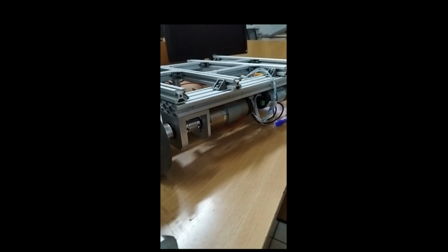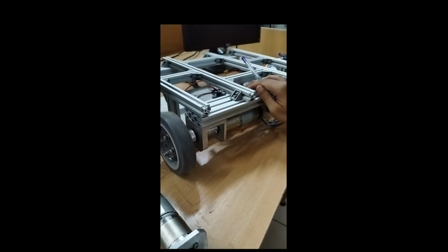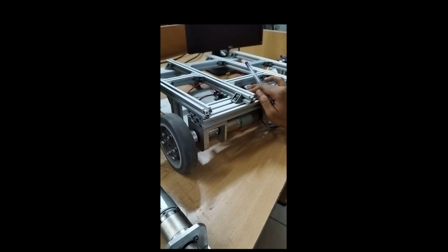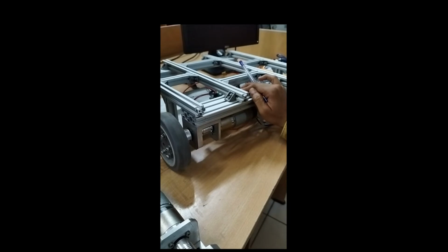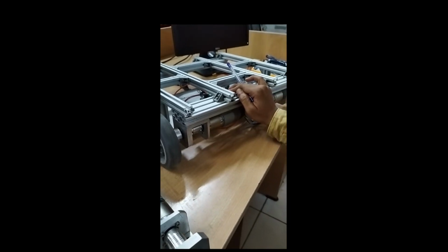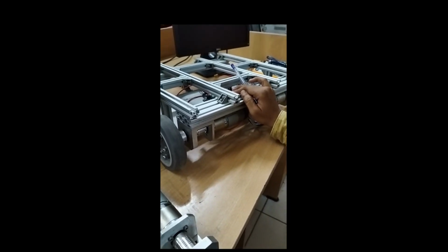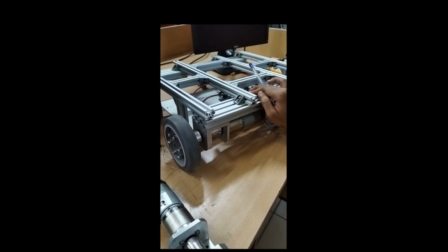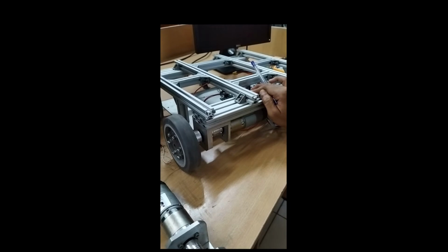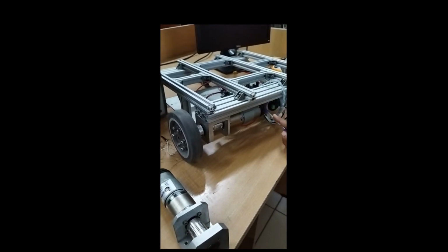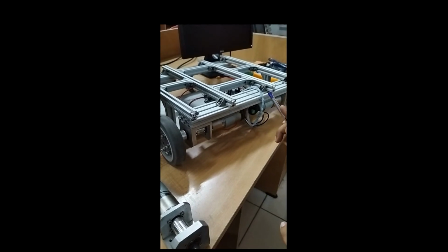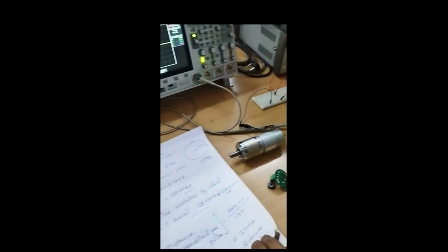So we have 3 millimeter accuracy. For example, if I want to make this robot travel 6 millimeter, I can drive this motor until I get 2 pulses. If I get 2 pulses, it could have traveled 6 millimeter. That is how it works. So up to millimeter accuracy I can make the robot travel forward as per my expectation. That is the beauty of the encoder, where every 3 millimeter the encoder produces 1 pulse. That is what you need to understand from this discussion.